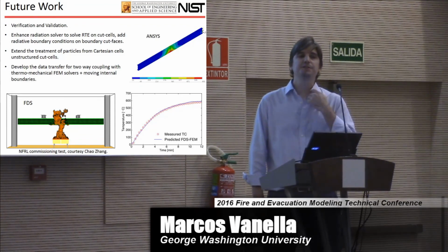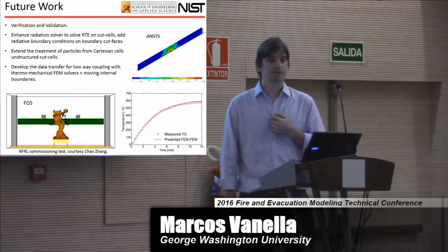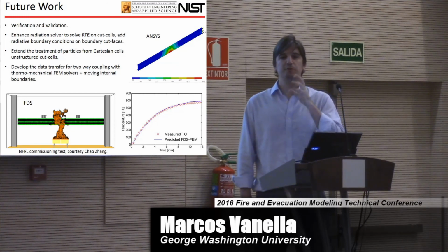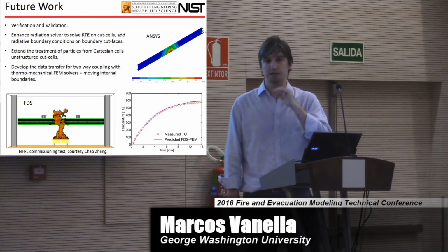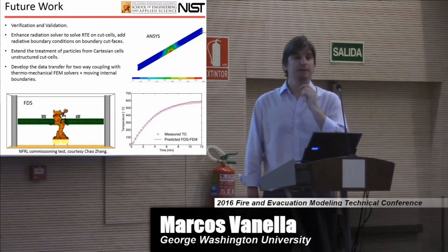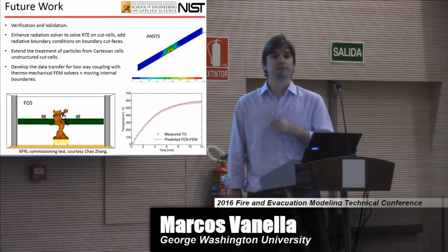Yes, and this is a problem not only in moving boundaries, but also in stationary boundaries. In general, when you force the velocity field inside the solid, and also you use the reconstruction outside, you might end up with very large divergences. For example, in case of incompressible flow, that will give you spikes in the pressure.